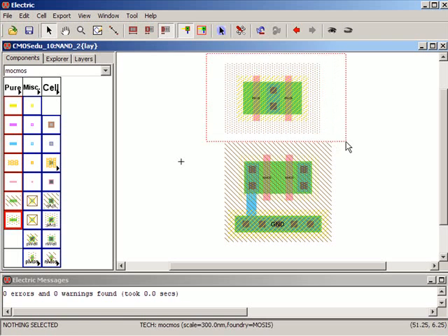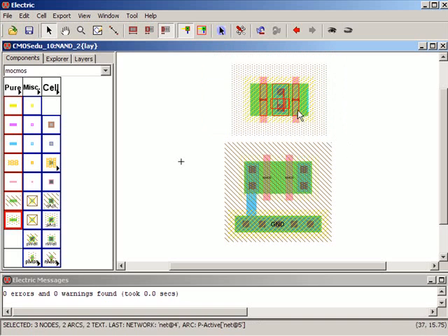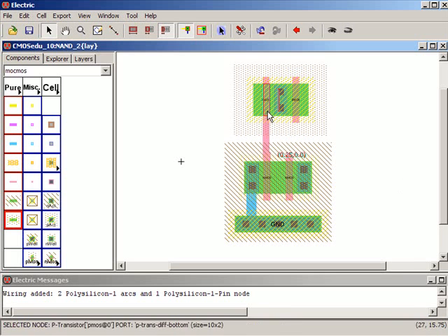So I'm going to move this over a little bit, center it up. Actually, I wonder if I can slide this over, because that would be nice for, let's DRC that. Okay, no error. So let me see if I can left click, pull down. And let's see if I can slide that over just a little more. Still no errors. And let me see, I could slide this one over, I guess. But I don't want to make this part wider. So instead I'm going to come down.